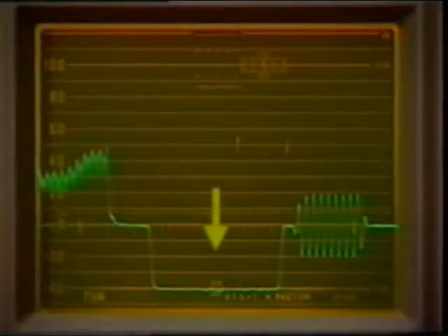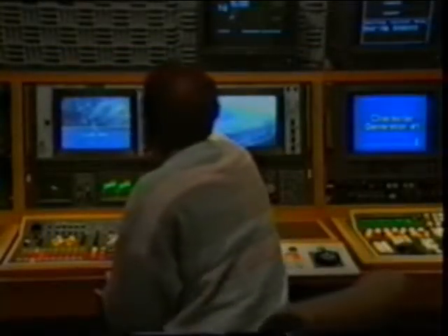On the waveform monitor, we'd be looking at the horizontal blanking interval. On the Vectorscope, we'd watch the color burst. Timing the video system prevents horizontal jumps or color shifts in the picture when switching between video sources. Now let's perform a system timing.